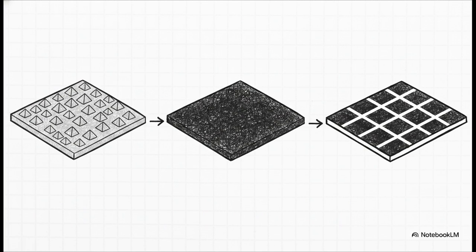During the actual semiconductor fabrication, we use chemical etching to create literally millions of microscopic surface pyramids. This is a neat trick. It traps the incoming light and minimizes reflection. Then, we apply a really thin silicon nitride anti-reflective coating, or ARC, via plasma deposition. This is actually what gives the solar cell its iconic dark blue or black color. Plus, it passivates the surface to drastically reduce electron recombination.